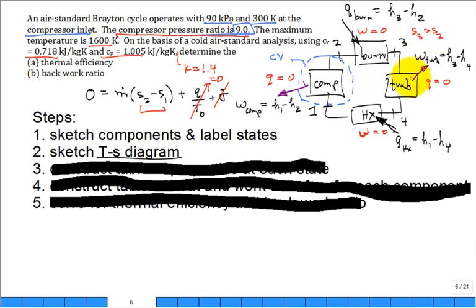All right, how about now compare S3 and S4? They're equal. And then here, I know that S1 is lower than S4 because there's heat out. Okay, so now I could probably do a pretty good job of this temperature entropy diagram. Maybe I tuck it in down here just for space purposes.